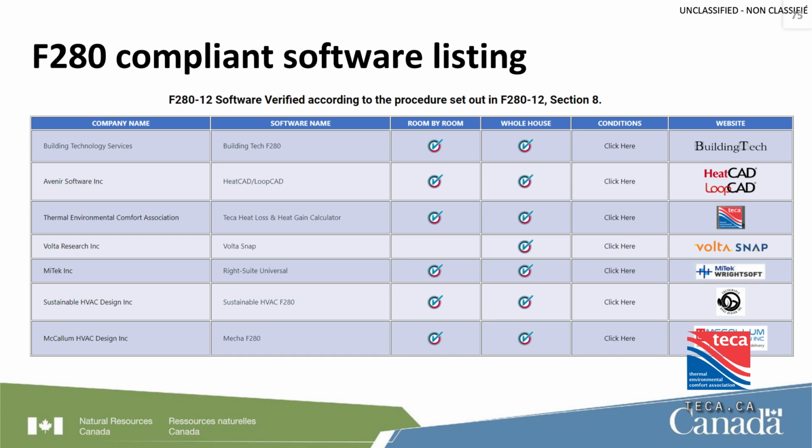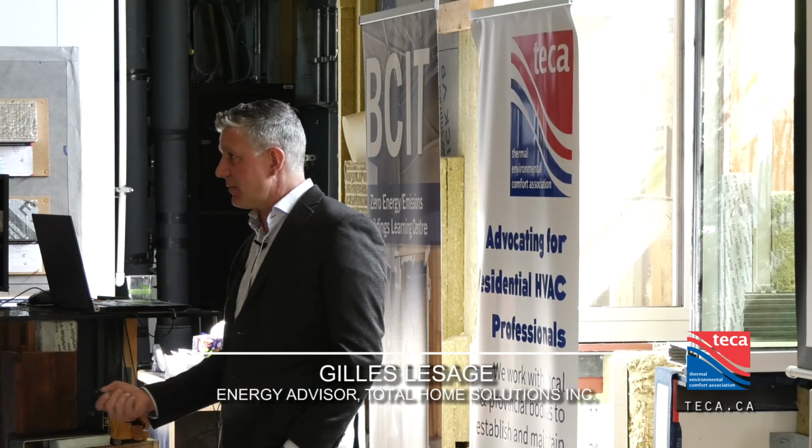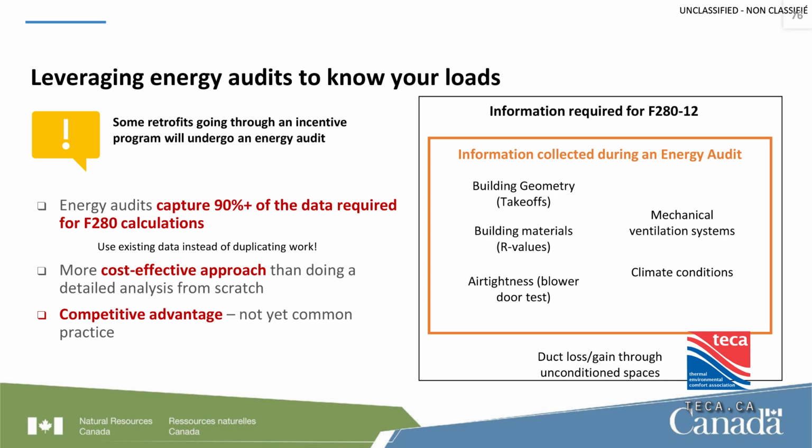Okay, so when it comes to a full room by room heat loss calculation that you may be performing, if you have the option of speaking with or have a relationship with the energy advisor that may have done an energy audit on this particular house, there's a lot of information there that can be shared, that can be used for inputs for your room by room.